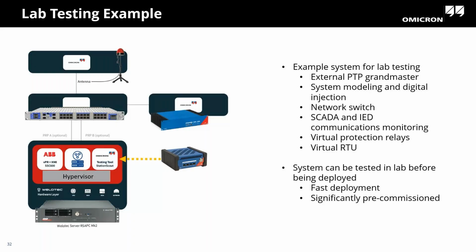And so in a lab, you can add in the virtualized testing tool here, but then just hook up an additional external switch and utilize additional testing tools. For example, we were using our modeling-based tool to then test the protection on those virtual relays, and had an external lab-based PTP clock. So where this could be really powerful in the future is that with a virtualized environment and virtualized relays, you can actually simulate your entire power system in the lab, take your entire server out into the field and deploy it, and you've basically already tested everything.